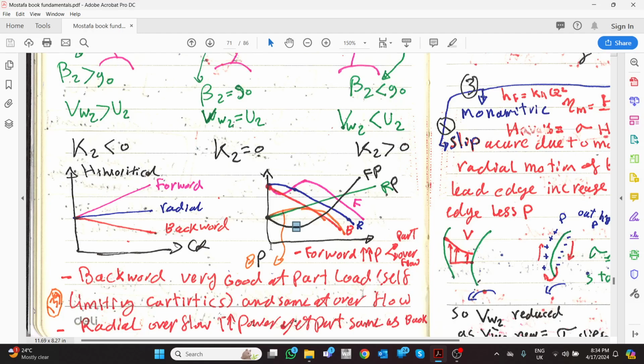Again, if you have this flow, this system curve, then you start to open the valves. So the system curve starts to go in this direction. While it is going in this direction, the pressure required for the system should be less, because you are coming from high pressure then to low pressure.